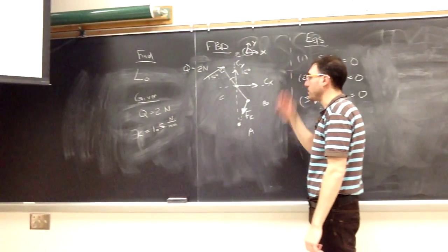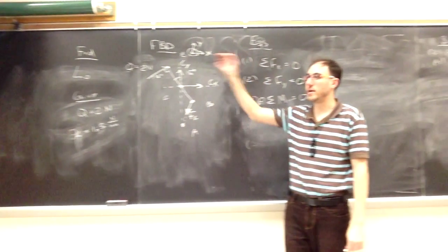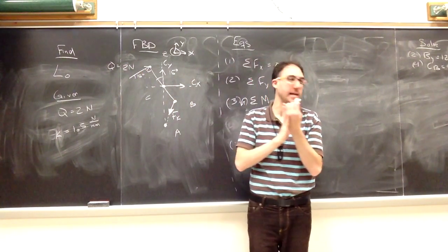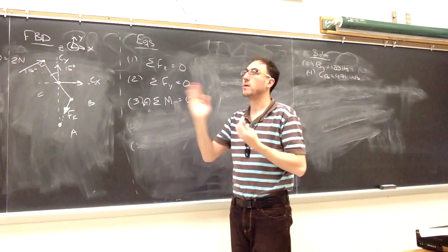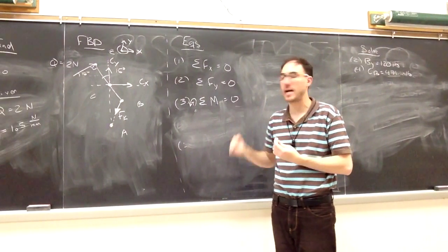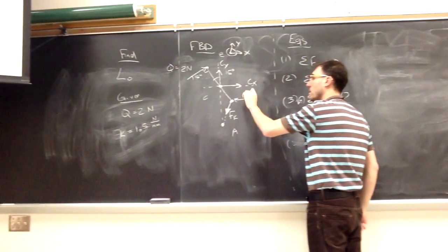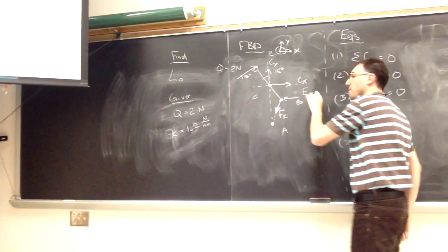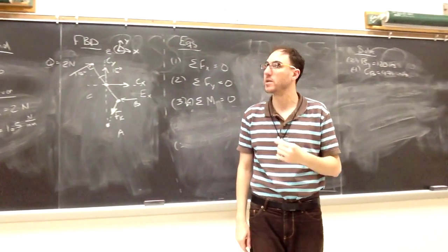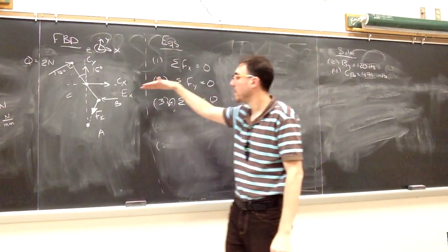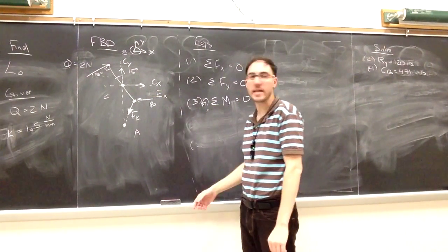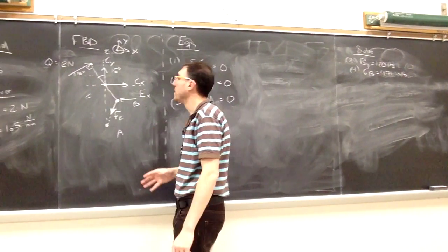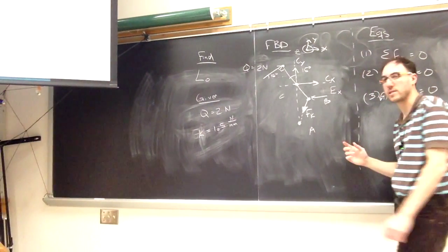And what other force or forces or moment acts on the switch, at least in our free body diagram step? There's a normal force at E where the bottom of that switch is resting against the wall. So there's this contact force. Now, like in the last one, we're looking at where it just breaks contact with the wall. But in the picture, we still will have Ex, that normal force. The normal force is always normal to the surface. And since at that point it's a vertical surface, that means normal to that, we're going to have this horizontal force Ex, which will drop to 0. At least we've accounted for all the forces acting on our object. There's no couples in this case, but we have all the forces that act on our object.